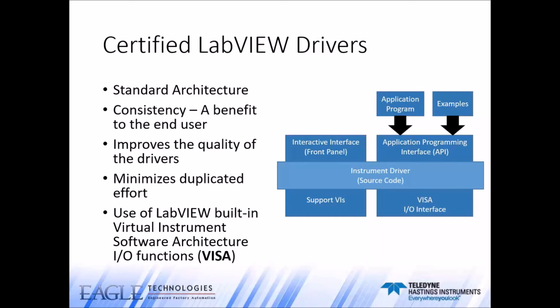For example, instrument drivers often call the default setup VI during initialization to set the instrument in a state that allows for robust instrument control by the rest of the instrument driver VIs. Only the initialize and the reset VIs use the default setup VI as a sub-VI, so it is considered a support VI. Certified LabVIEW drivers follow all the mentioned design guidelines and are rigorously checked by NI and the driver developer before being released.